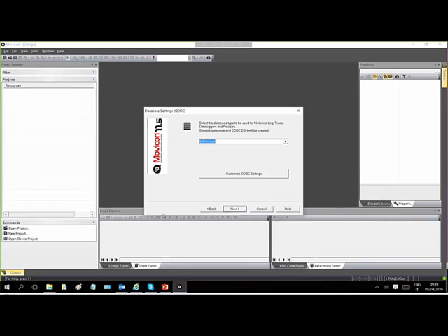A database interface for a SCADA is a very important part. How do you store your field variables, your pressure, your temperature, in a database? Movicon is open to interconnect all the most common database engines. For example, SQL Express, the free of charge version. We have the dedicated plugin. I will talk about how you can interface your project with the database in the second part of the webinar. So for the moment, I will leave the default, which is a Microsoft Access database.